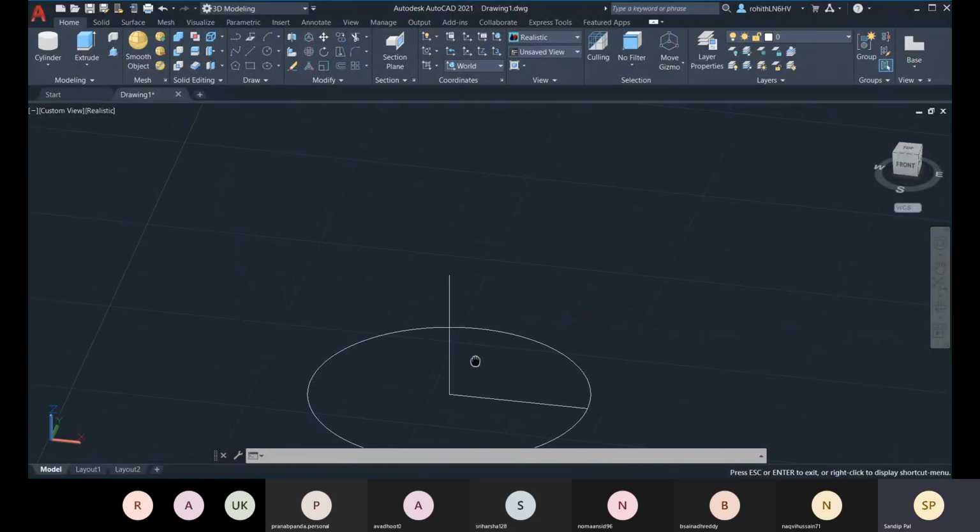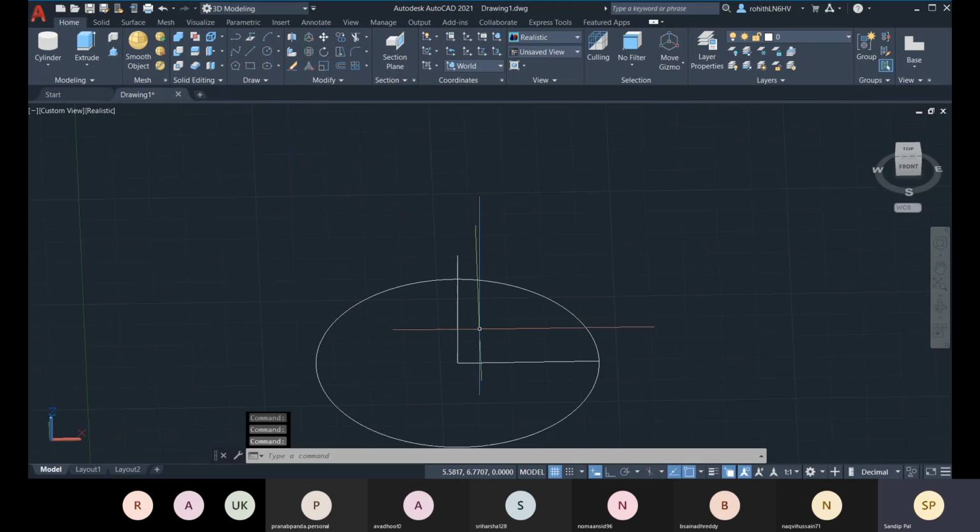As I have mentioned, this is how you create a cylinder using cylindrical coordinates. First, you specify the center point or the first point, then the next point within the XY plane at an angle in 360 degrees, and then another point in the Z direction. For that, you just provide the point value.